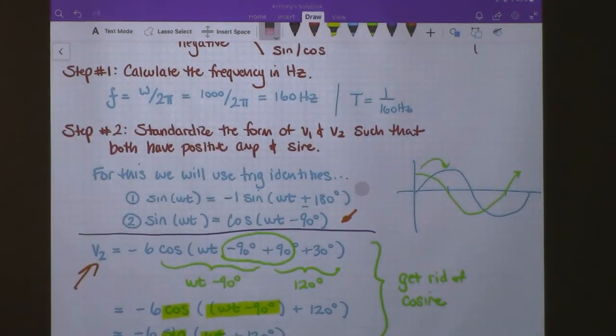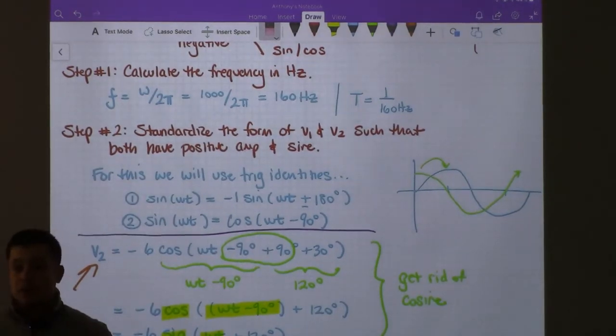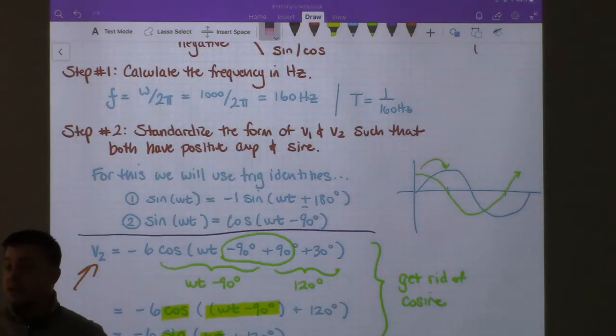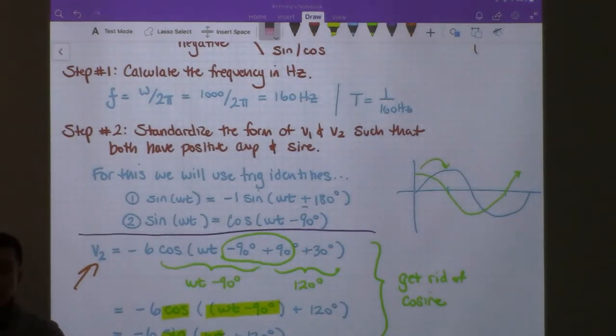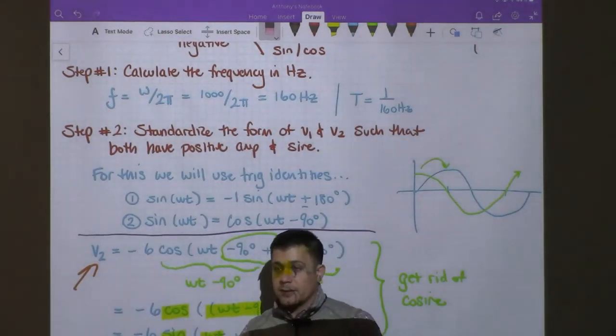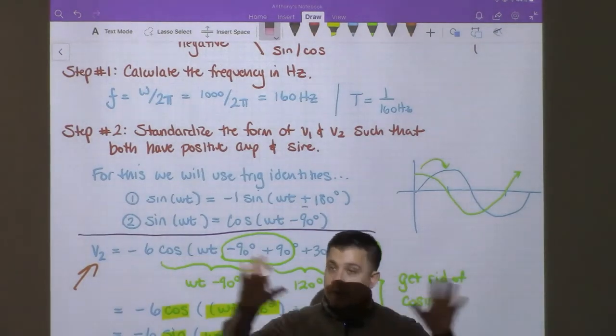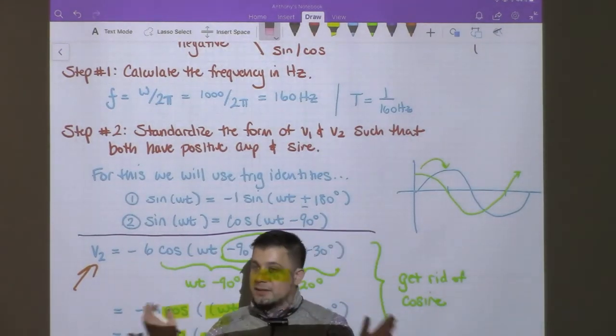Maybe I've just misunderstood. Fundamentally, what is a phase shift? A phase shift is moving right and left, but from where? Exactly. This is something we touched upon last time, and it's an important point. A phase shift is a referential value, so there needs to be a reference for it. It's actually a lot like voltage. Voltage has no meaning if there is no reference or ground to which it's referenced. So a phase shift for a single waveform, the only waveform that exists in the universe, doesn't exist.